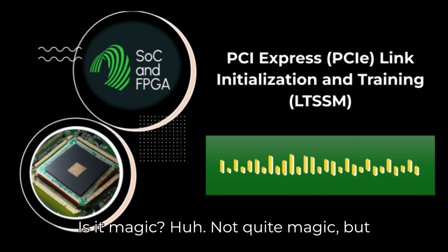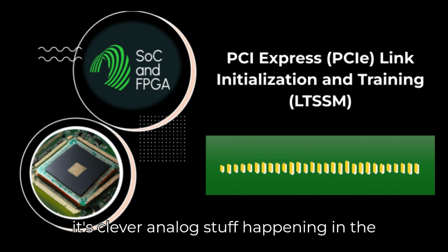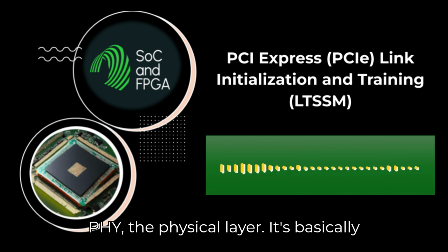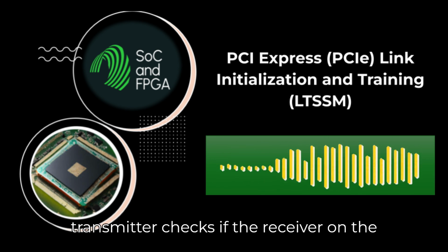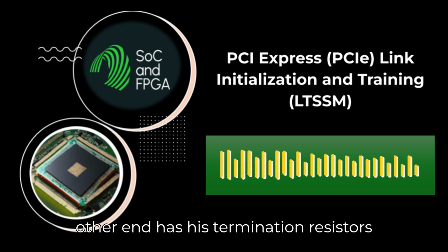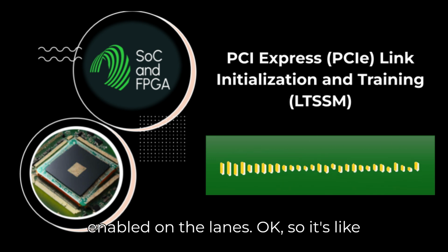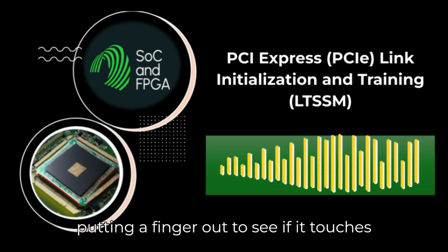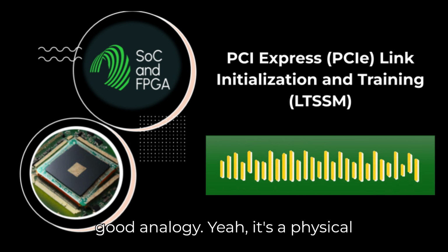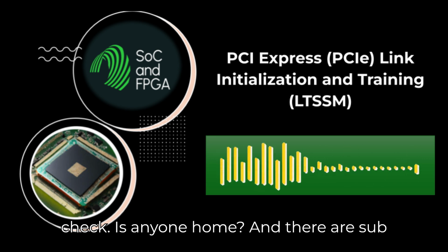Is it magic? Not quite magic, but it's clever analog stuff happening in the PHY, the physical layer. It's basically feeling for electrical resistance. The transmitter checks if the receiver on the other end has its termination resistors enabled on the lanes. Okay. So it's like putting a finger out to see if it touches something, electrically speaking. It's a good analogy, yeah. It's a physical check. Is anyone home?